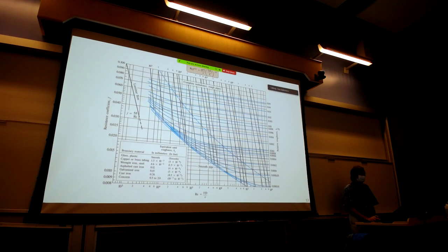So now we have 2 coordinates with which we can enter that Moody diagram. From the top, we know that Re f to the 1/2 is 48,200. From the right, and you can see I drew that contour, and obviously it doesn't have a value right on one of the black lines. So you're visually looking in between the two.